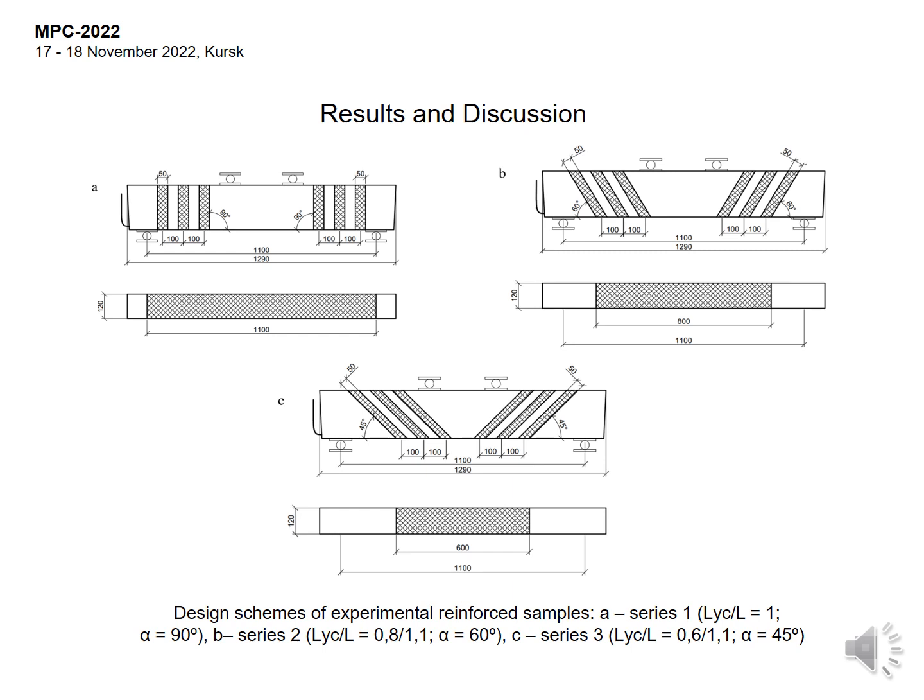The calculation made by the authors was carried out with the aim of rational use of composite materials when performing experimental studies on strengthening reinforced concrete bendable elements. The values of the destructive moments allowed us to plot the effective operation of the composite material along the length of the element.